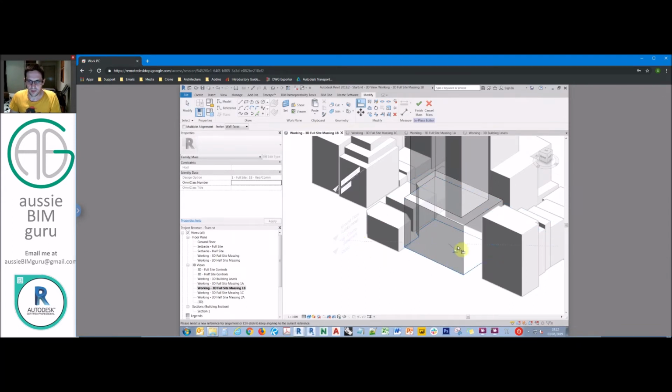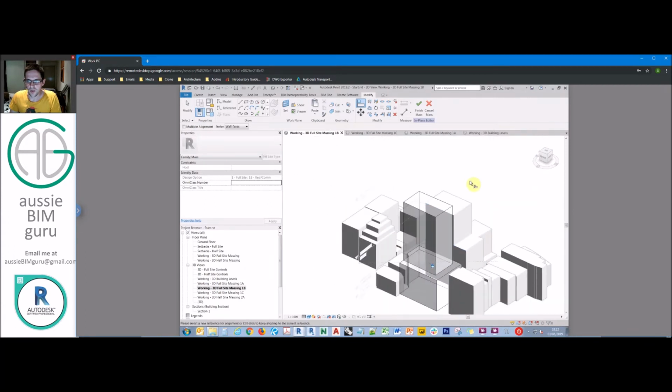And we do need to realign all our profiles because when you copy a mass, it no longer keeps the same constraints. So you do have to re-establish those, unfortunately. But it's quite easy, just align to the levels as you go. And now these are reconstrained.